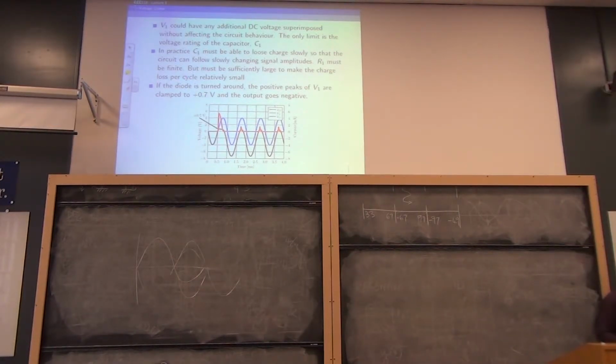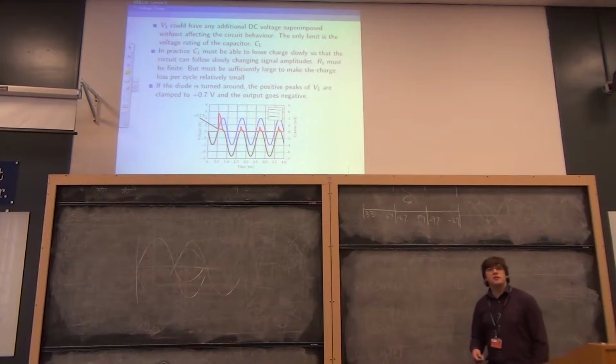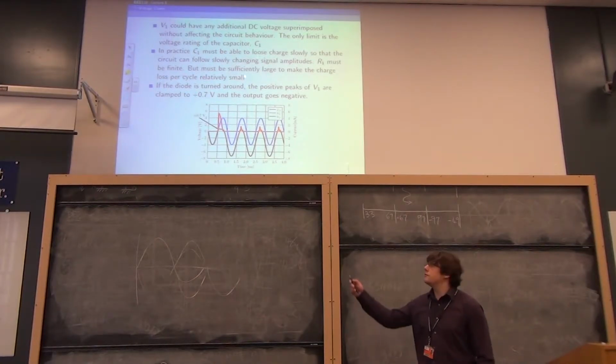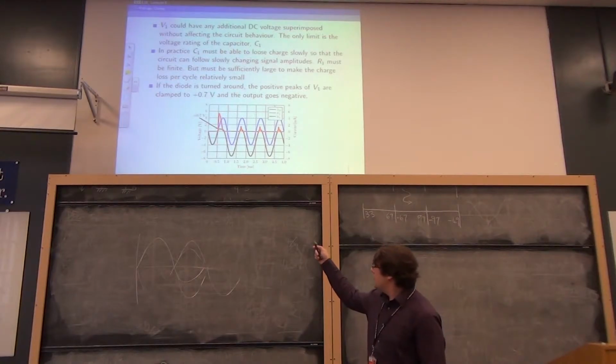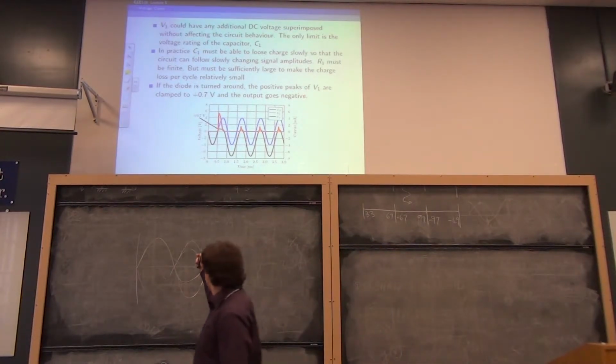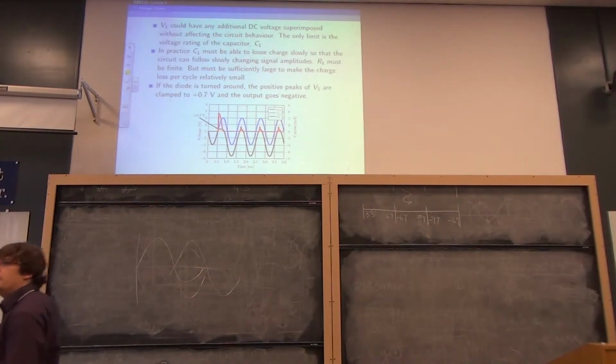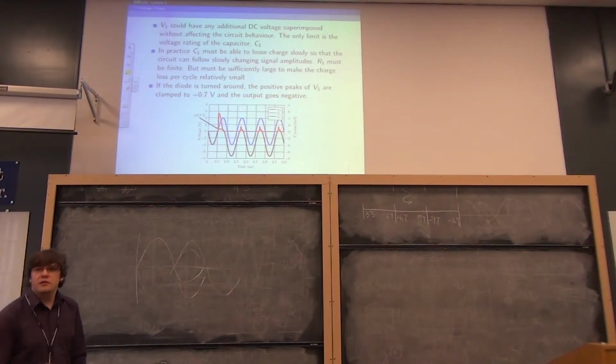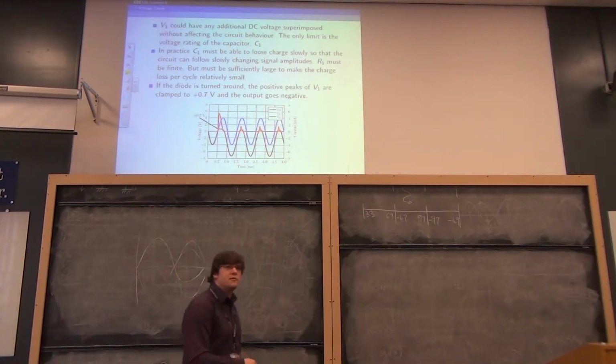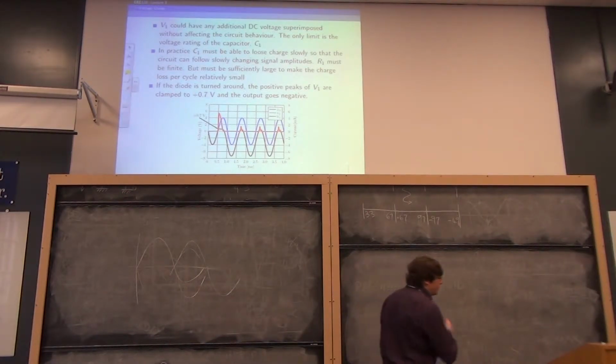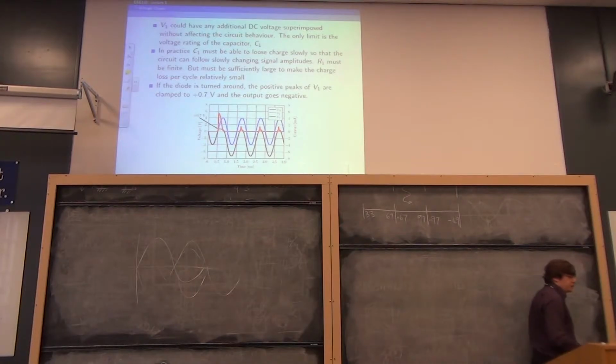And if I was to turn the diode around, the waveforms will all be reversed, and you clamp the positive half cycle, not the negative half cycle, and that will produce this diagram here. So this is exactly the same operation using exactly the same description, and with respect to time, all the things happen in the same order, except that the diode has been reversed. The consequence is that when previously it would be reverse biased, it will now be forward biased, and vice versa. So we'll end up with the situation where we clamp the positive half cycle instead.